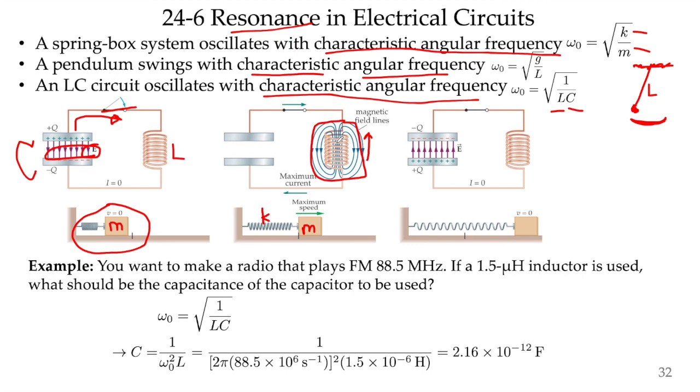Again, after some point, the inductor is going to create its own back EMF. Back EMF is basically the inductor itself acting as a battery in the opposite direction. If it acts as a battery, it will start to charge the capacitor, right? So the capacitor is discharging, charging the inductor, and then the inductor charges the capacitor back, and this happens back and forth continuously.